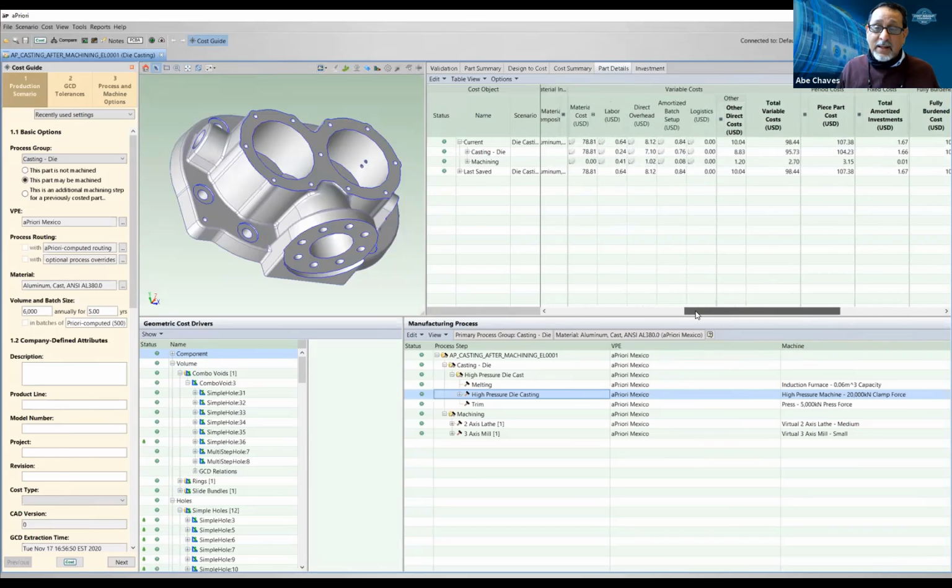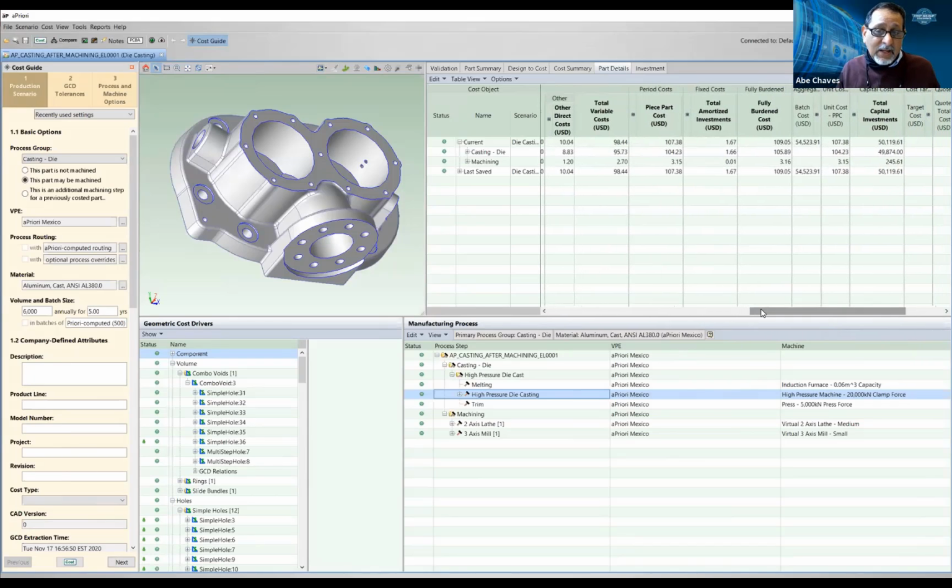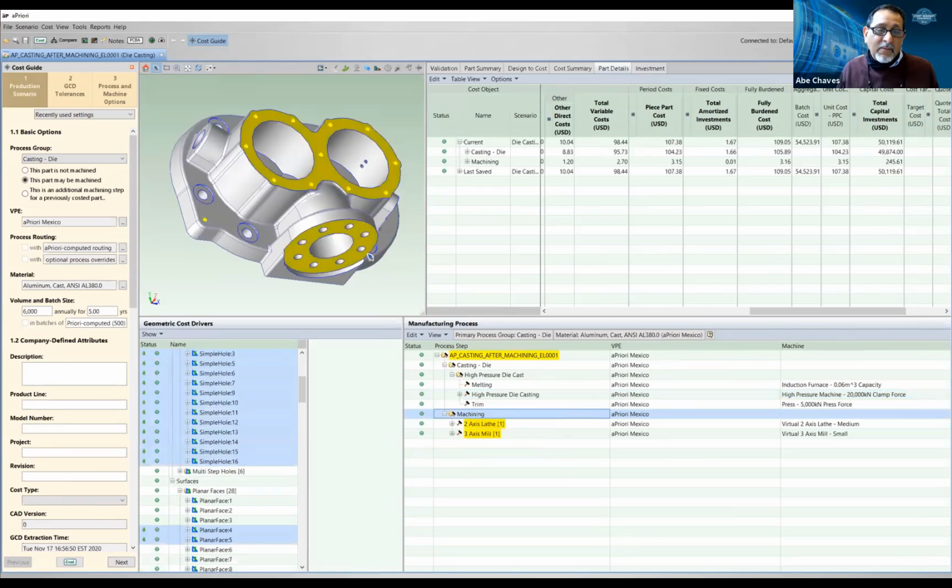And the supplier might say, no, I don't even know what the cycle time is because I don't machine that part. You see, 90% of the castings I make, all I do is basically machine some faces and make some holes, but I don't have any turning mills. So this part required turning, so I sent it out to a sub-supplier. So then I have to create the parts, package them, ship them, have a supplier do the machining, then package them, ship them again. And I'm charging you for all that cost and a premium because I'm taking a risk.